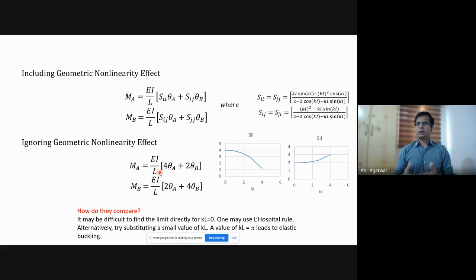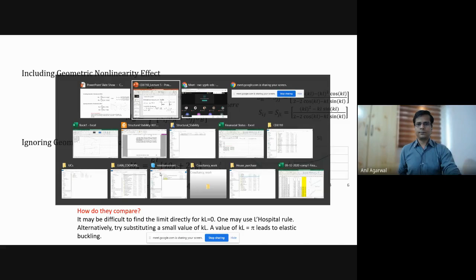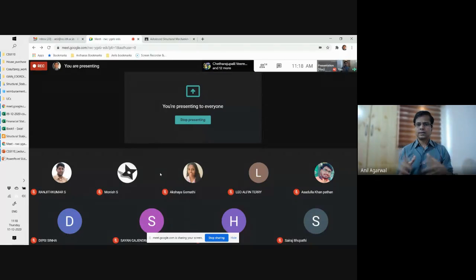We developed the formulation for a geometrically nonlinear beam member. In case of a geometrically nonlinear beam member, since it was deforming, the rotations at the end change. If I apply a moment here and there was axial load applied, then because of the presence of this axial load, for a given moment, I was supposed to get a certain theta for a linear member. But for a non-linear member, I'll get a larger theta. You follow me, right? There is an amplification factor. Correct?